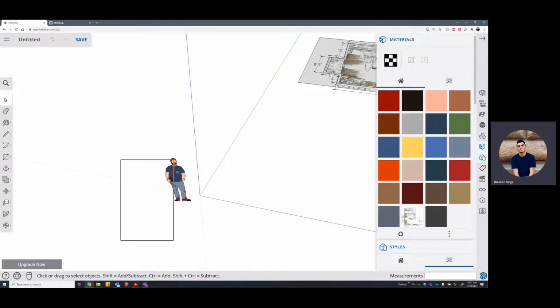Basically, when you select from left to right, you have to envelop the whole object in your rectangle, otherwise it won't select it. So if I do this and leave his foot out of the frame, it won't select him. But the other way around, it'll select everything that it touches. I can even touch his heel and it'll select him. And it doesn't happen with left to right. This is important when you have multiple little objects.